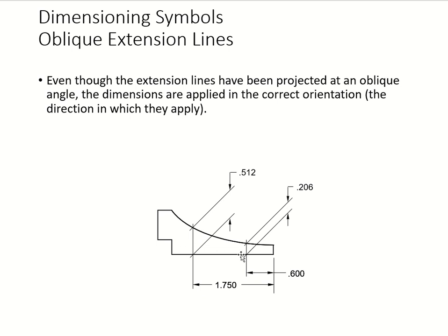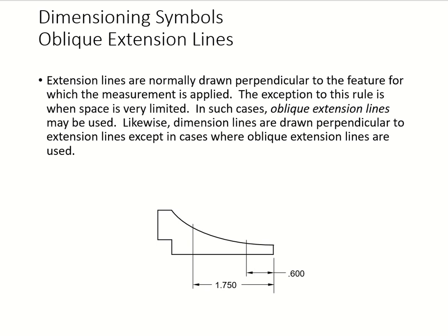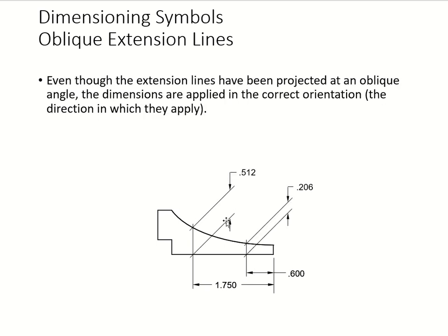Sometimes you're going to deal with the oblique angle. At that time, we can give the dimension line a little bit slender like that. Not perfectly perpendicular like this, but slanted. Of course, here the arrow is out and the value is out because of the limited space that we are defining between here and here, here and here.